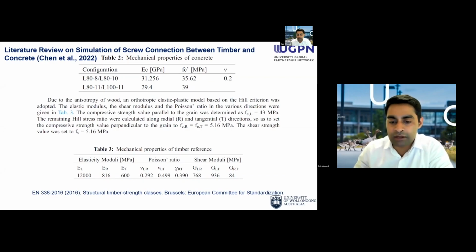But fortunately, I'm a bit encouraged to see that they are able to simulate it within the transverse orthotropy, the orthotropic simulation that I just discussed, and a constant Poisson ratio. So if this simplified method works for them, for engineered bamboo it should work. That means at least initially we should be able to get some results, and anyone who is interested in modeling engineered bamboo behavior can refer to this paper as well. It's very recent and just published this year.